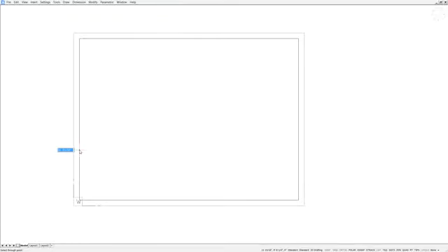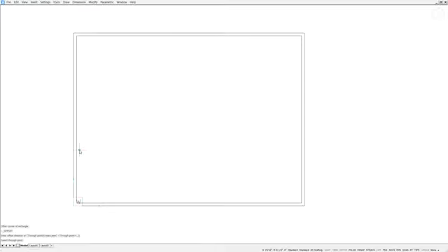All right, so I'm going to use the offset command, and maybe I'll just offset this. We'll just say 6 units to the inside. And I can continue working there. Again, no object selected. If I right-click, I could draw a line. I can acquire points, very much like you're probably used to working if you're like me, coming from AutoCAD. I can use acquired points. I can drag over using ortho and polar. All right, so I won't spend a lot of time on that, but I just want you to be aware of the quad because it's a super easy way to access your tools without having to take up space on your command line.